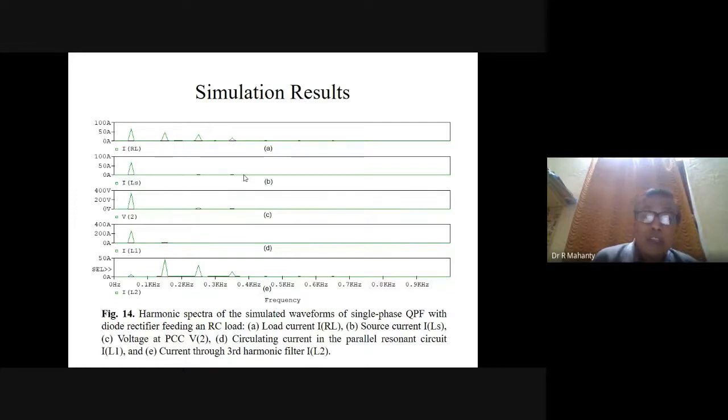So we realized a large value AC capacitor, and then using it, we established that all the harmonics can be eliminated if the shunt passive filter is tuned at the dominant harmonic frequency. At the same time, we can also provide reactive power to the line, and thereby improve the displacement power factor also.